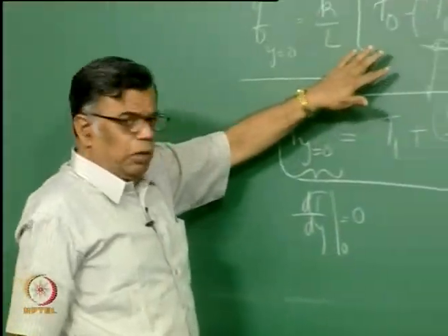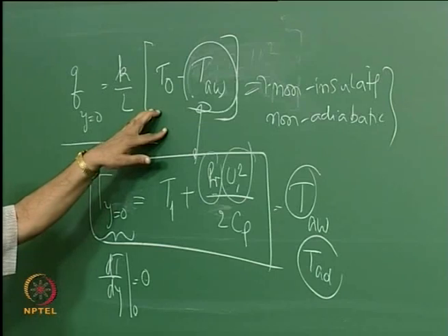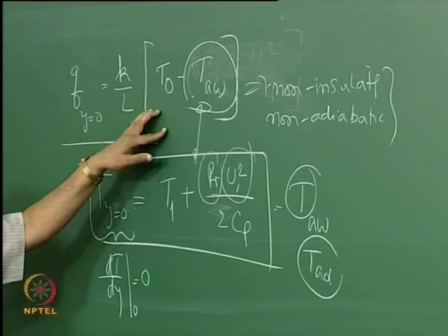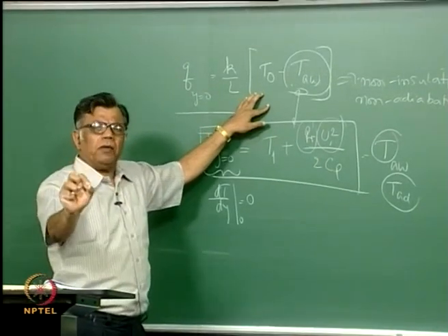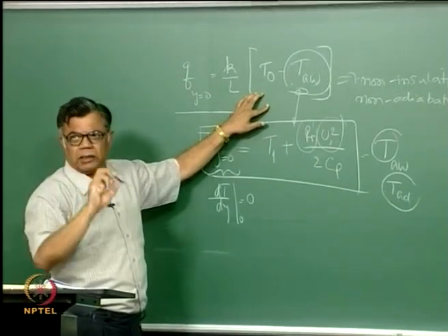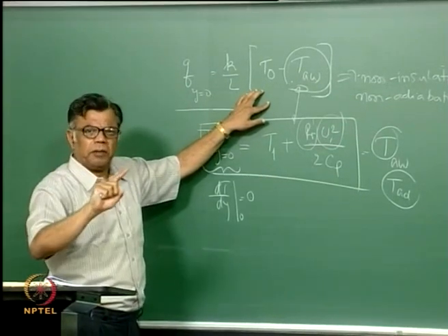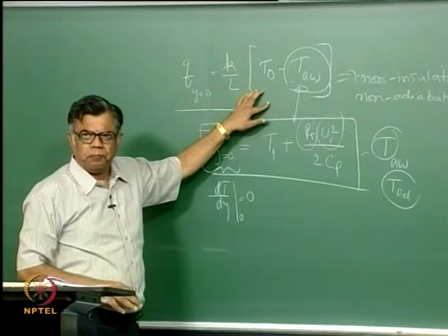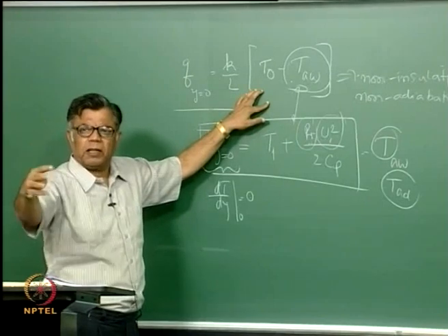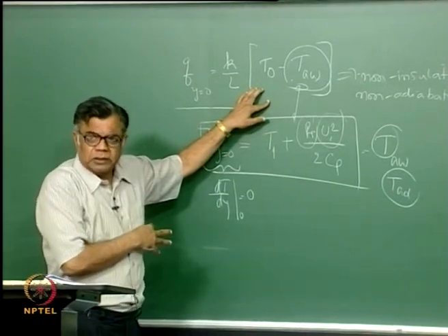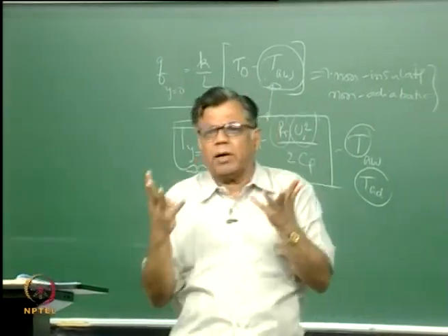Now when we got this expression, we did not use the term high velocity flow anywhere. We did not say it is high velocity flow. We went on saying Prandtl, Eckert. What is the value of Prandtl Eckert? Meaning the effect of the Prandtl number and the velocity is coming into the picture. We simply did not say high velocity flow, because you have done high velocity flow in forced convection, where you said du/dy, Eckert number. Now, I did not say high velocity. I simply said we will take mu by k (du/dy) whole squared into consideration. Let us see what happens.